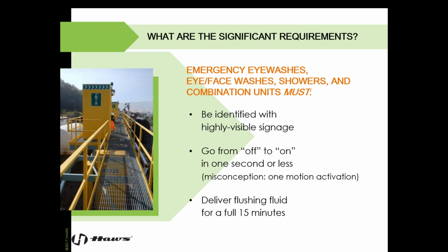All emergency eye washes, eye face washes, showers, and combination units must be identified with highly visible signage. So most manufacturers of emergency eye washes and showers provide that with the equipment, but we want to ensure that it is installed properly, it is highly visible, the colors are recognized. We'll get into color requirements a little later on, and just make sure that that's a part of the training for your employees so they know where to go if an incident were to occur.